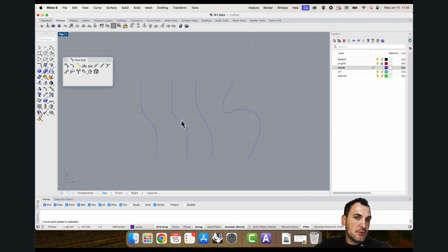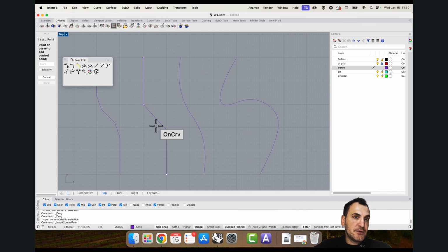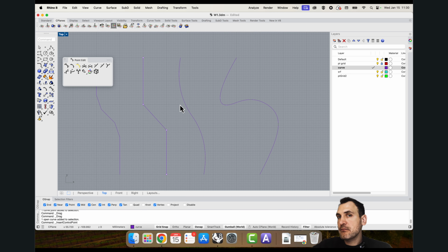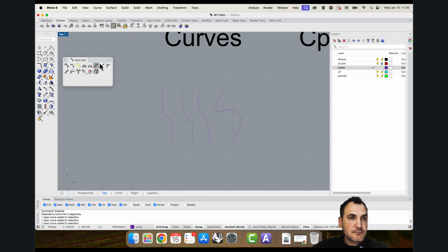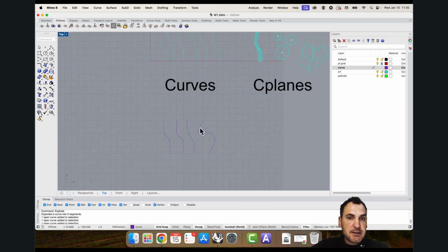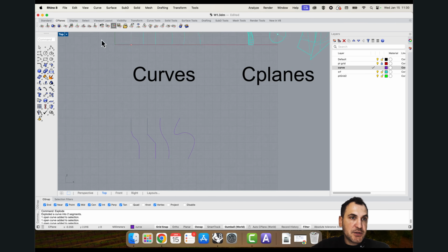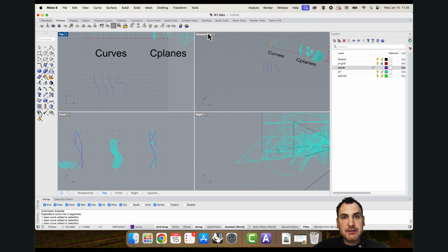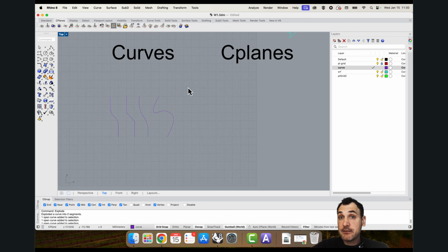And you can do this for any type of curve. So you can do it on a polyline, on arcs, but arcs would cause discontinuities because they're separately drawn. So if I, for instance, explode this, you would see I get 2 arcs, and these are basically subsets of circles. Okay, so those are essentially curves, and I want to show one more thing, which is the handle curve.